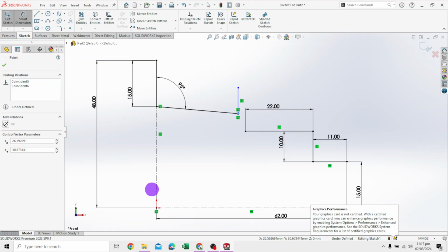Okay, so I figured out how to go about this. Basically use the smart dimension. Before I accidentally put the smart dimension from here to here, we don't need to dimension this. We need to dimension the tip of this to this. It needs to be 62. And now what I'm doing is from the tip of this to here, we need basically a curve that comes in from this to this. The curve isn't specified, but the distance from this point to that is specified. So that's what I'm doing. If you directly do it, it won't let you.